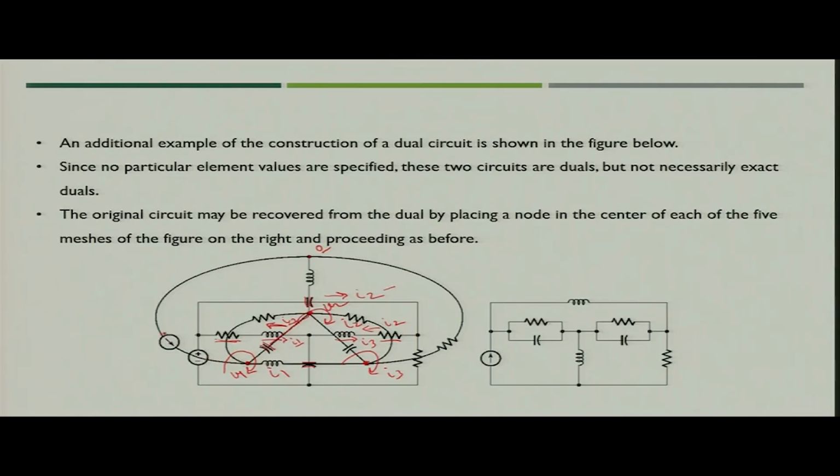So, that is why the dual of this is represented as a current source with current in this direction, because if it is giving current in a clockwise direction to the mesh, that means that the corresponding dual current source will have current flowing inside the node. So, using the circuit and the duals of each and every element, we can draw the dual circuit. Now, let us rearrange it.